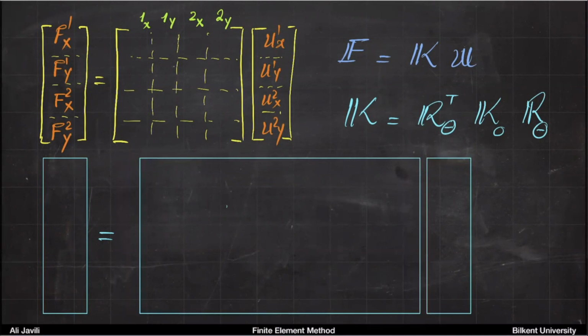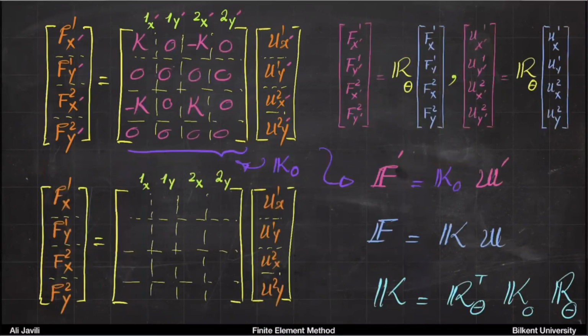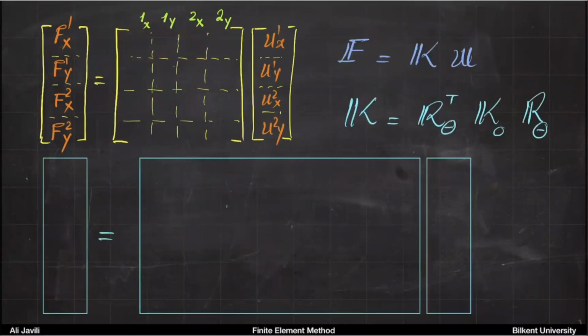So in that coordinate system, remember we had constantly this K thing. So K, minus K, minus K, K. Imagine that K is out, and then we have 1, minus 1, minus 1, 1. Okay, so I'm going to take K out of the system. K is just the coefficient on the left-hand side of that. And then again, if you have a truss, it's something like EA over L. If it's a spring, it's just the stiffness of the spring.